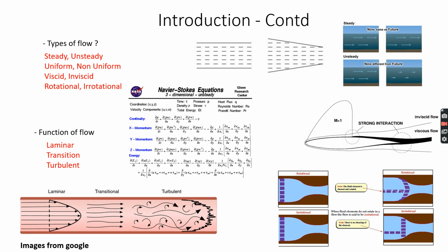Transitions can be observed through certain phenomena, such as on a flat plate boundary layer, where you can see the formation of Tollmien-Schlichting waves, and they pair up into three-dimensional horseshoe vortices and their rotation, finally leading up to turbulence. Whereas on the contrary, in jets and the like, you can see a vortex rolling up and vortex pairing up, and the vortex building into a complex network. This depends upon the point of inflection and the point of non-inflection for the inviscid and the viscid flows, which is a deeper topic that we're going to discuss later.